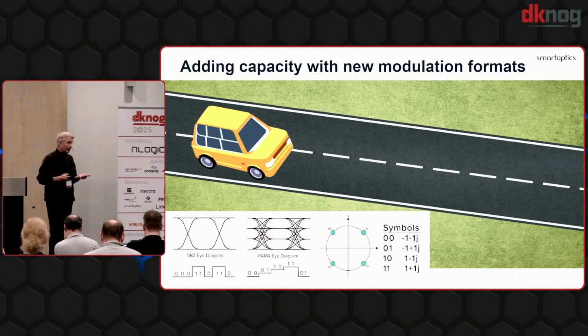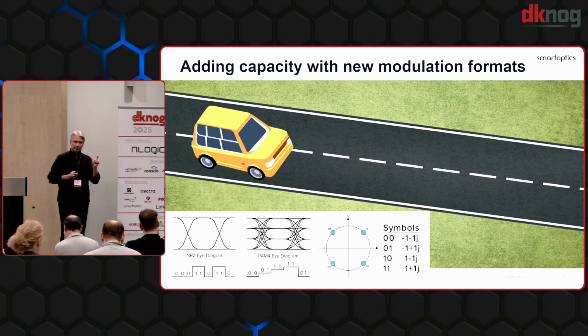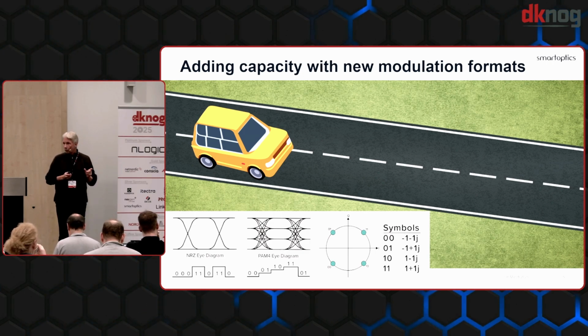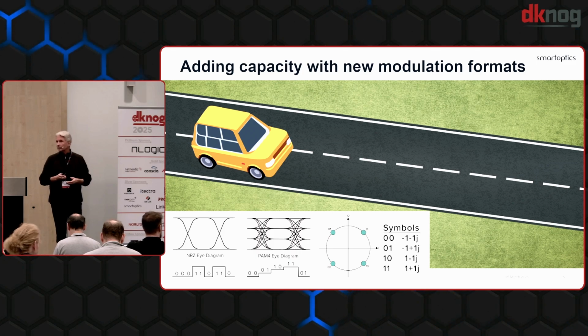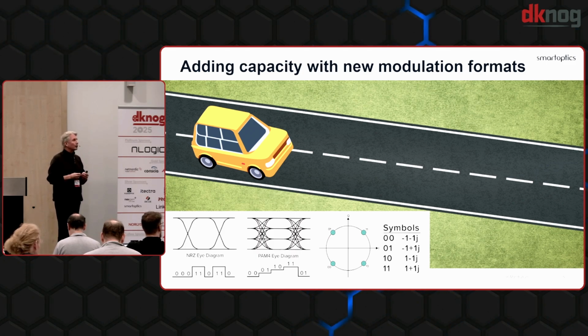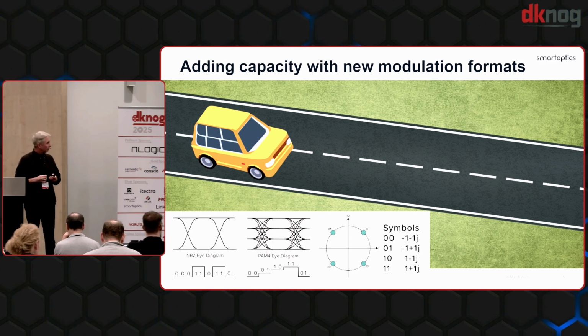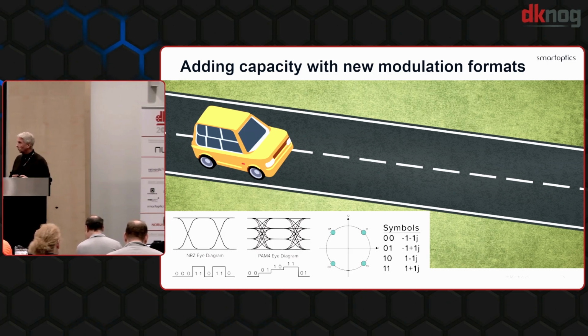In an LR1, you use the second technology. You use 50 gigabit per second transmission, but you have a modulation format of PAM4, so then you get 100 gig based on that. If you want to go long distance, then you actually need to use other types of technologies, the coherent technology. In this case, I show a constellation diagram of a 100 gig QPSK modulated signal.